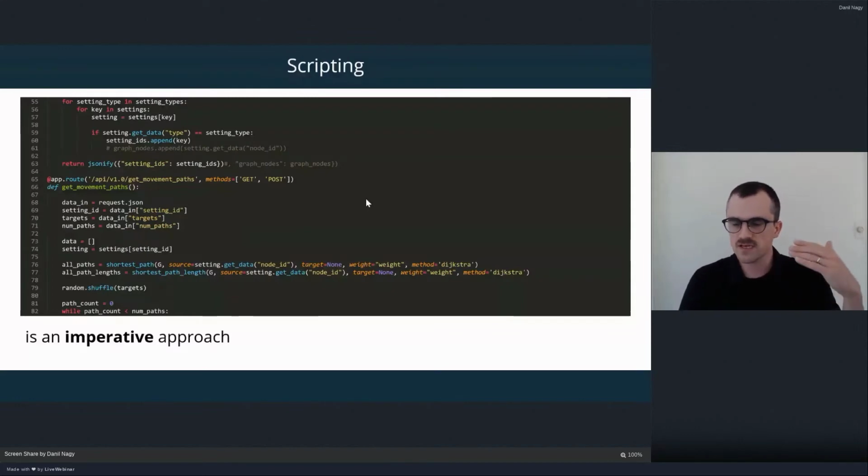And you have all these kind of workarounds for making it work in Grasshopper, something that would actually be much easier expressed in an imperative way using text-based programming. And at some point, you actually get into things, and we'll look at them in this class even, that are actually impossible to do in Grasshopper, like writing recursive functions. You just can't do it in a visual programming language, but you can do it in Python.